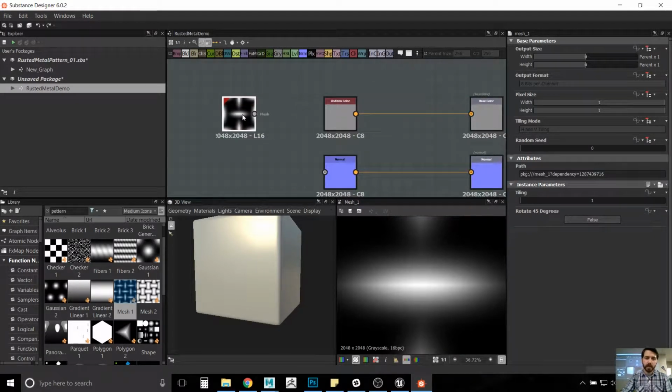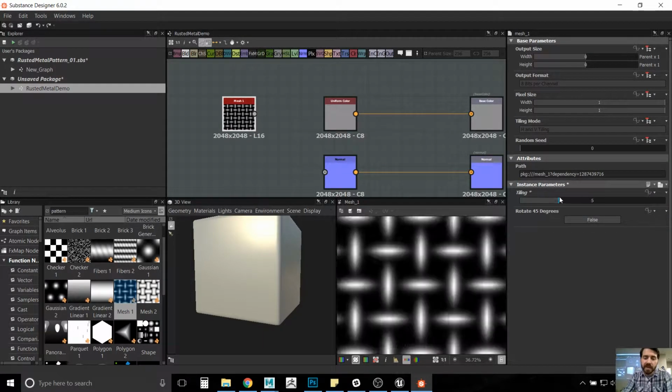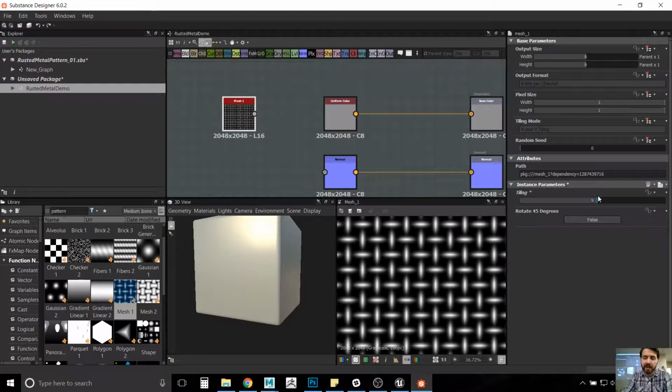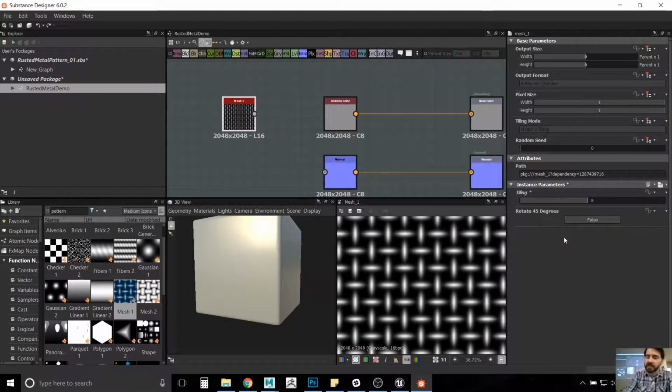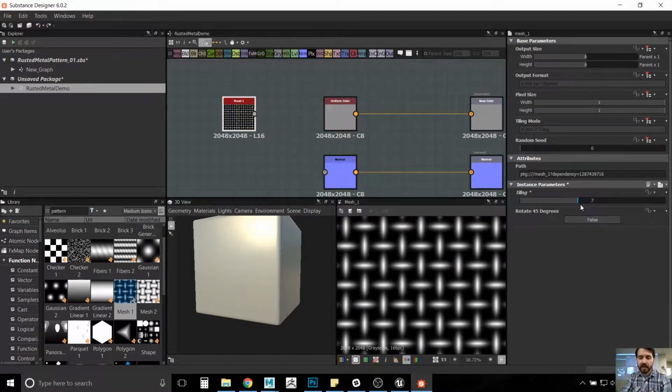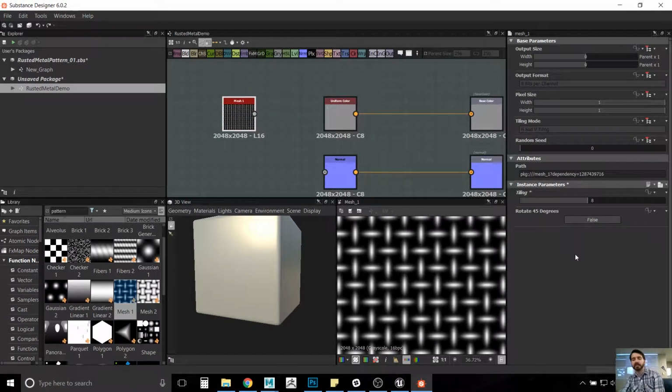So once we drag it in there, now we can actually make adjustments to it in our scene. What we're going to be doing is changing the amount of tiling first. So right now I want to change it to maybe tile 8 times, let's say. And you can just drag it left and right to tile it more or less. So 8's probably pretty good.